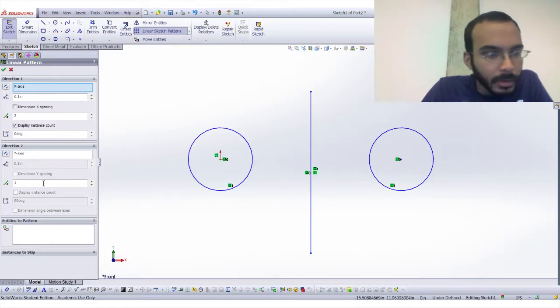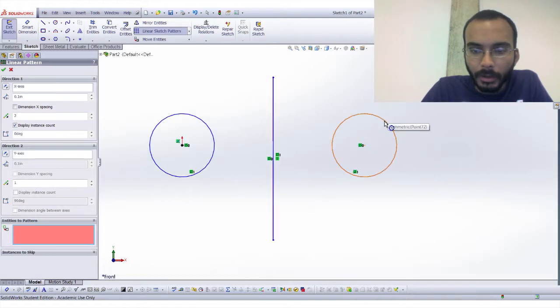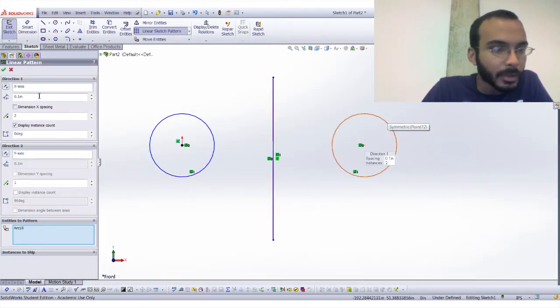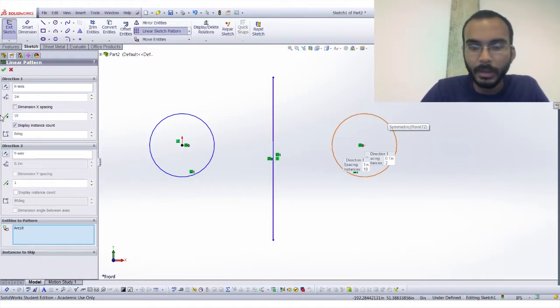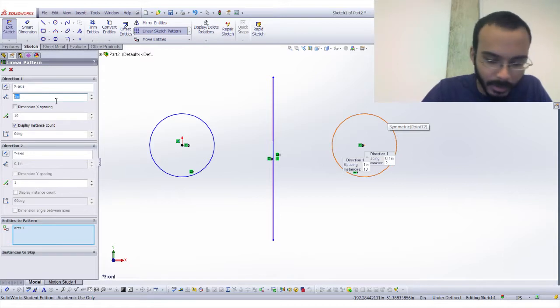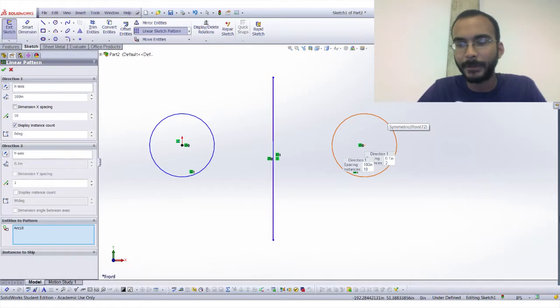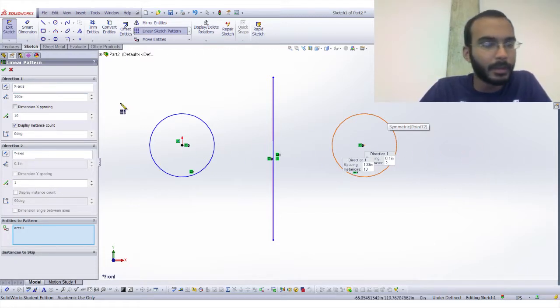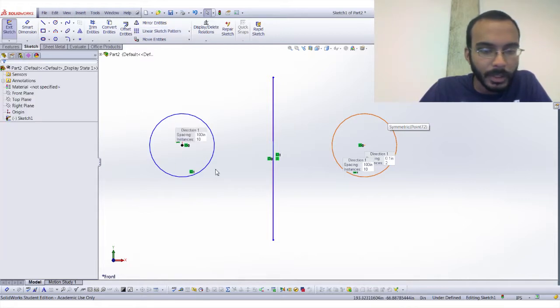On that same note, you can also use the linear sketch pattern tool to go about sketching. So you want to select entities to pattern down here, and it'll sketch whole patterns and things for you. So like all of those nice pretty sheet metal robots that have all the crazy numbers of holes in them, that's all from being able to do things like this. Wow, I'm drawing in way too large of scale. Okay, 10 inch on circle. Nope. All right, 100 inch on circle. There we go. Okay, so you can see that you get nice long chains of holes like you would.